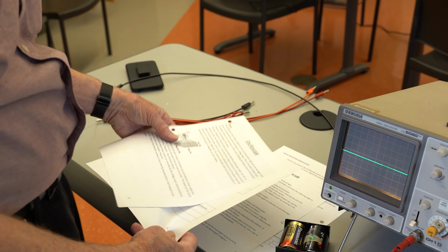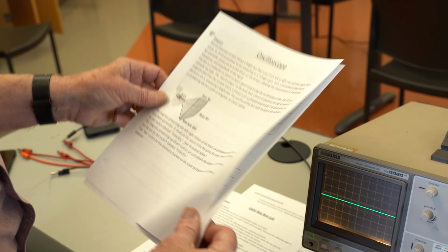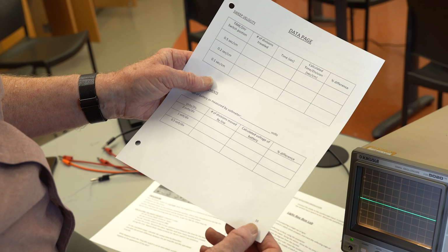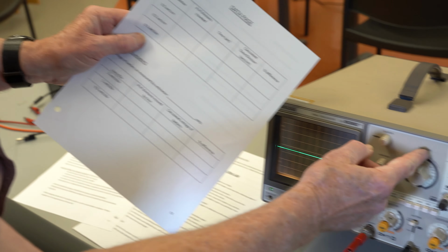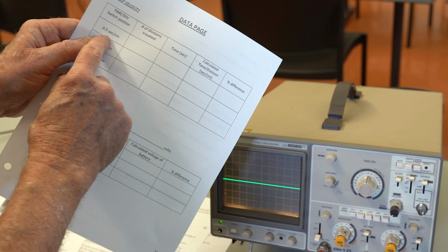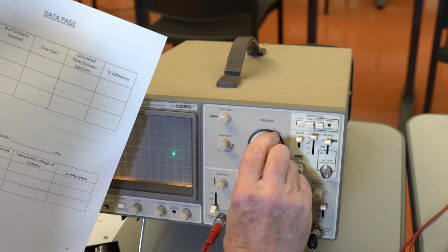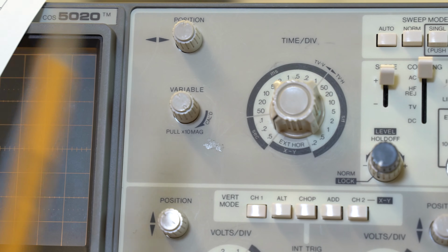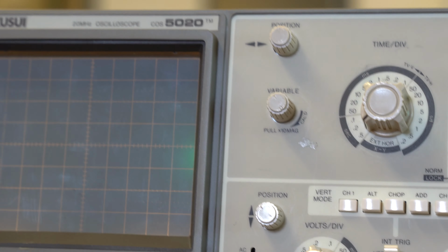We're looking at the oscilloscope handout in your lab manual. This is on page 51. And we're just going to jump over here to page 55 and take a look at what's called the sweep velocity, which is what's indicated on the time per division switch. So it tells us to set the time per division switch to 0.5 seconds per centimeter. So if I turn this to, that's the first setting, 0.5. It says 0.5 here, and this is seconds. And we're going to check to see if this is really true.